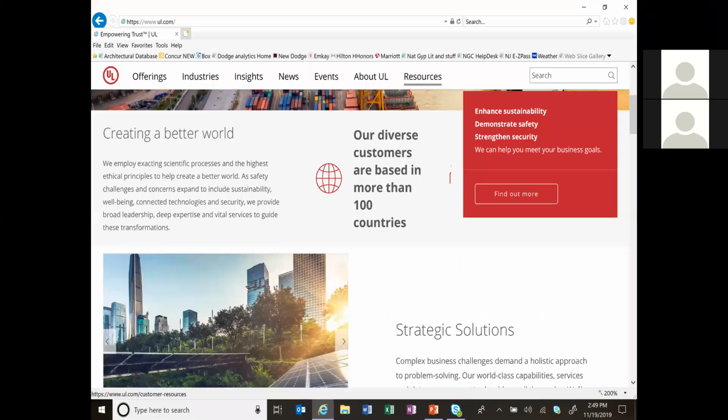So with that out of the way, with ul.com, again, a super large website. They do a ton of stuff. What we're going to focus on is just spending a couple of minutes finding a wall assembly with gypsum board and metal studs. And I'm not positive which one I want. If you know, for example, that you want to do U465, a very commonly specified wall, just Google it, Bing it, Firefox it, whatever. It'll come up very quickly that way. But let's assume you don't know. So we're going to use the UL website.